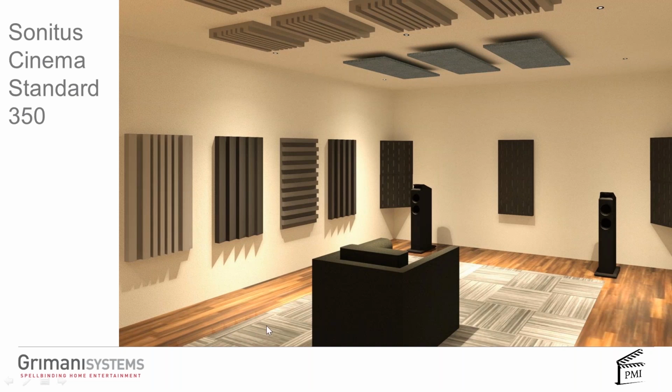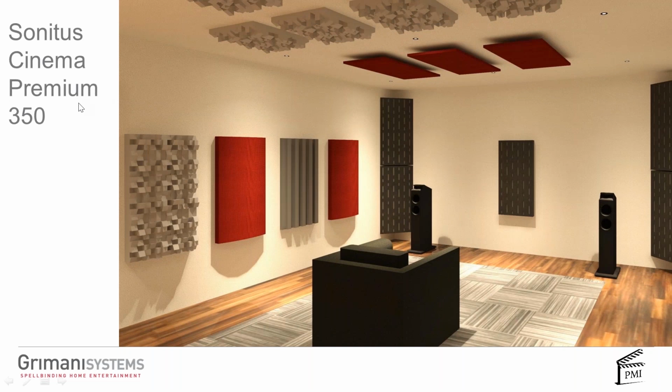That's an absorber. Okay. There's a higher end solution called a premium. Here's an absorber. Here's a 2D scattering diffuser, absorber, 3D diffuser. Remember, this is like the quintessential picture. Try to absorb at spread areas through the room. Right. Put 2D diffusion towards the front, 3D diffusion towards the back. On the ceiling, absorb towards the front of the ceiling.